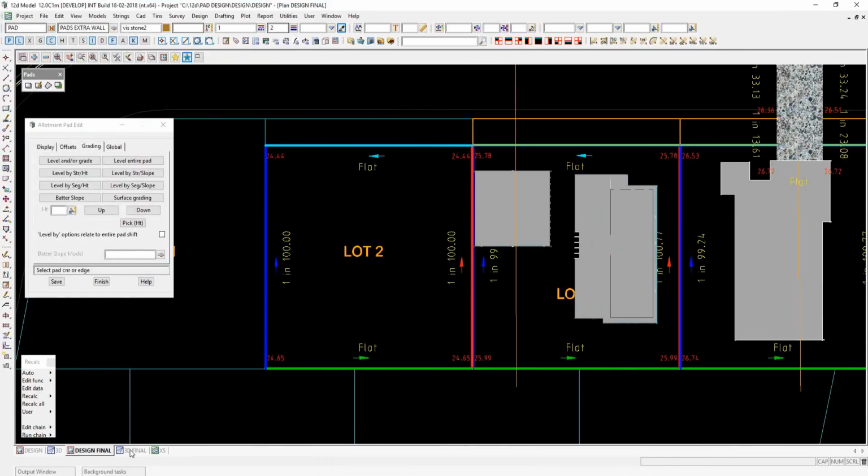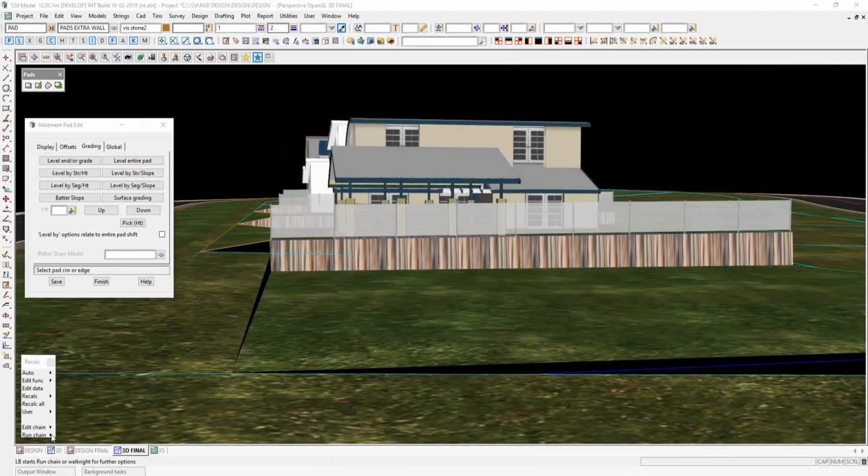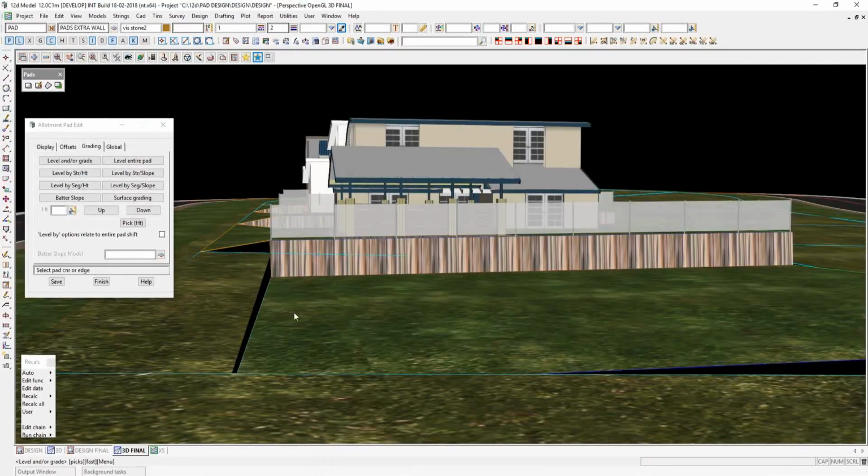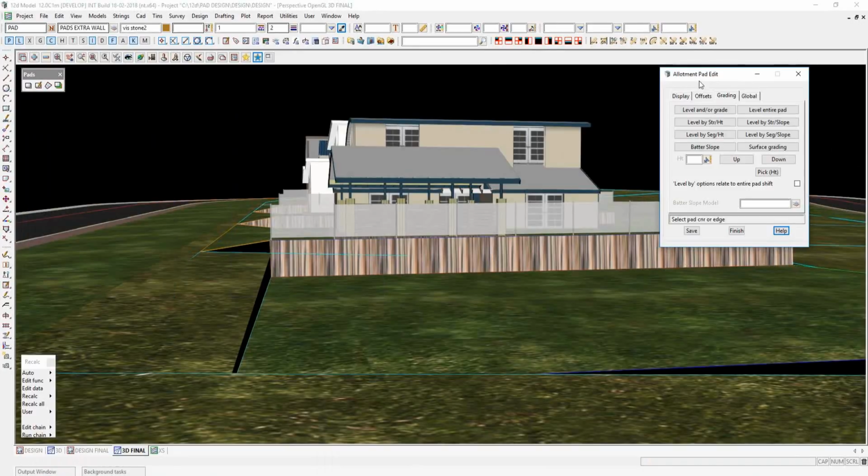So I'm looking at the pad now, say, okay, that's not too bad. I'll go back and run this again. Then it updates the pad, so the pad's fallen this way. It looks a bit high because you've got to be able to get the pad, as with these pads here, to transition roughly halfway across to go from falling away from the footpath to falling out from the footpath. And this all can get a bit tricky depending on how steep this road is.